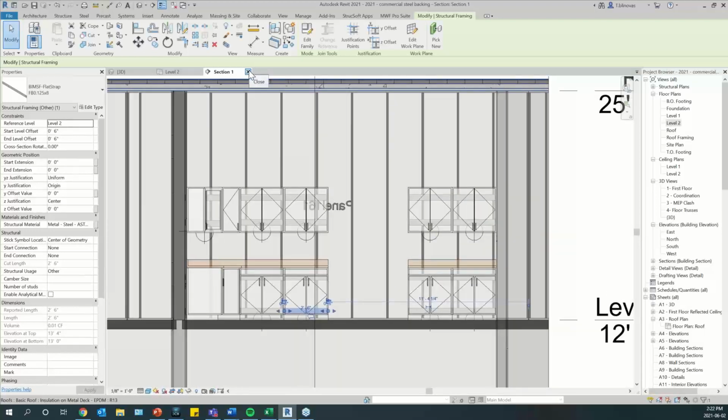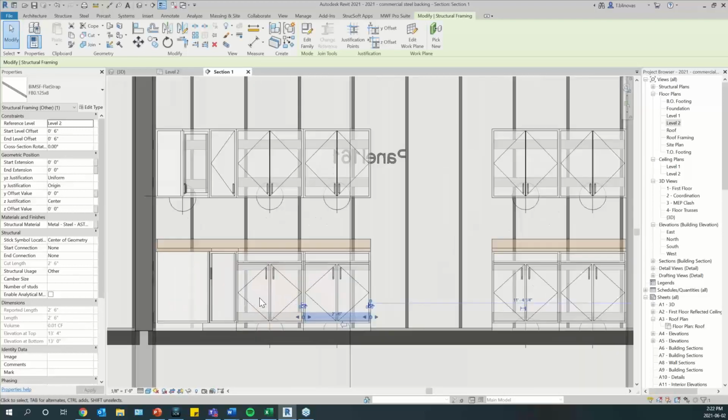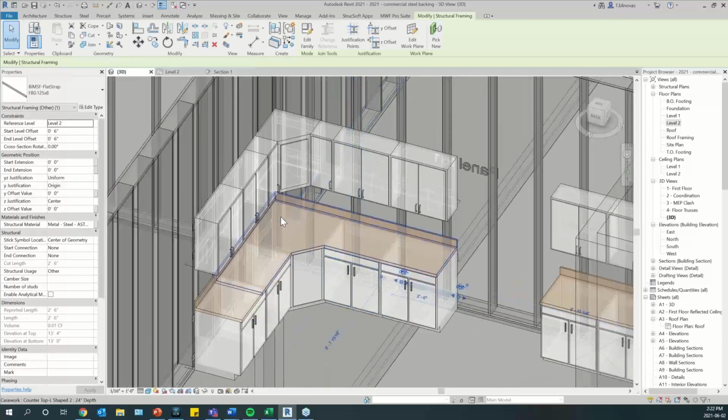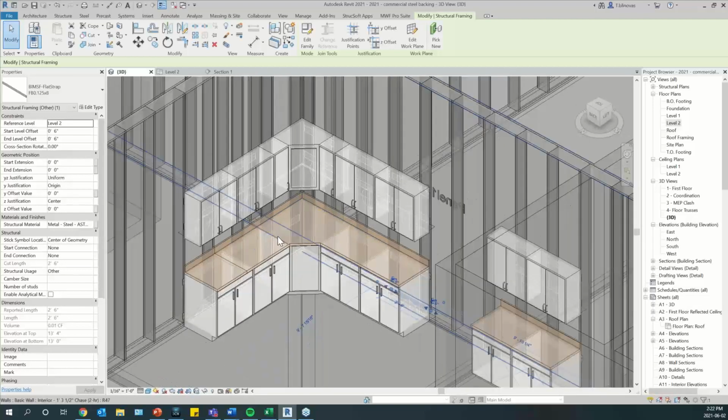So the other thing that you can do, in case you don't want pieces like that and you want a whole member all the way, is instead of adding rules to these cabinets, you can just add 2 rules for the corner one and extend your backing. So you will change the lateral offset and the length of the backing member. So let's try to do that.